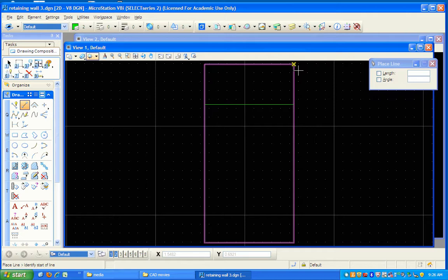So what we're going to do here is reference this front face again, origin, and we're going to come over 0.45 plus 0.075 meters. And I want to do orthogonal again. So now this area in here will contain the cap with a little space behind it as it's pictured. Okay, and that's really all we need on this layer.